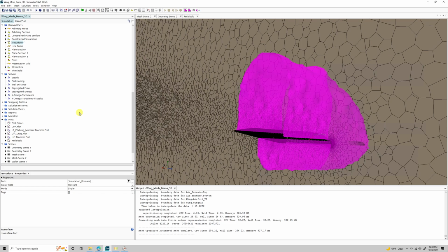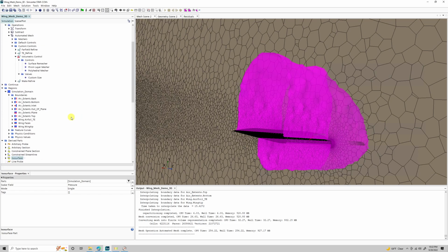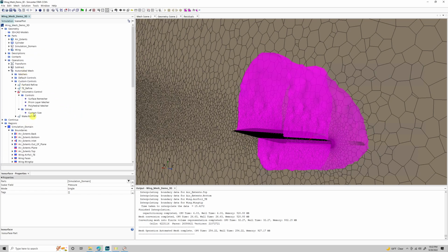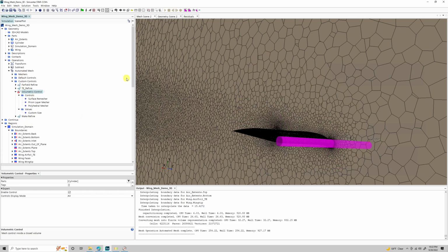It won't necessarily tell you that there's a problem, although they could, depending on how alert you were. We talked a little bit about volumetric refinements and how you can refine regions of the flow in three-dimensional space, not just surfaces. Also very powerful, though potentially dangerous.